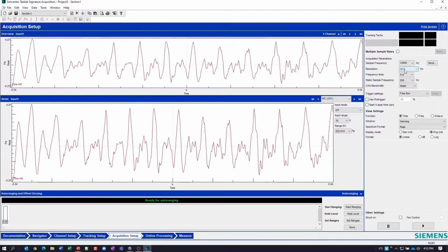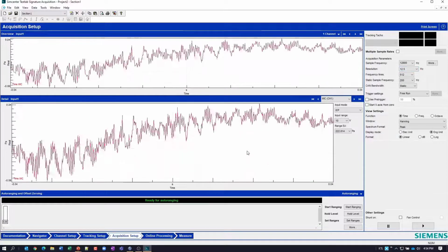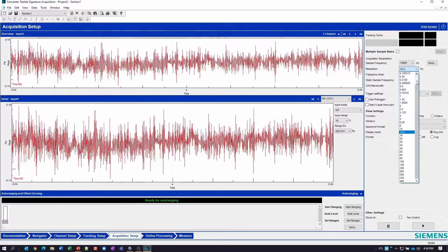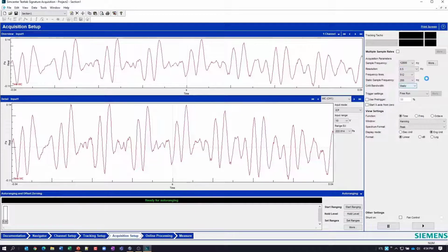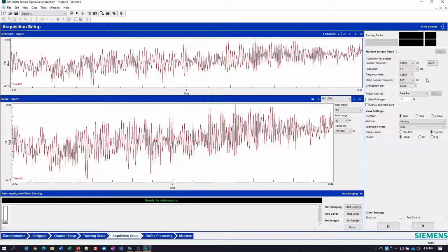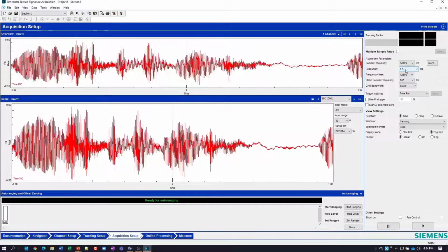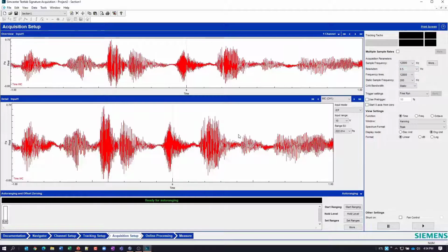So you see when my resolution is 12.5 hertz, in this case, I get a lot of updates per second on the screen. If I make this smaller and say 0.5 hertz resolution, now each average takes 2 seconds, or the inverse of this number. 1 over 1/2 is 2, and so each of these updates you see on the screen takes 2 seconds.